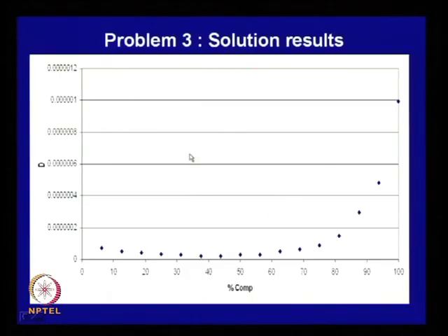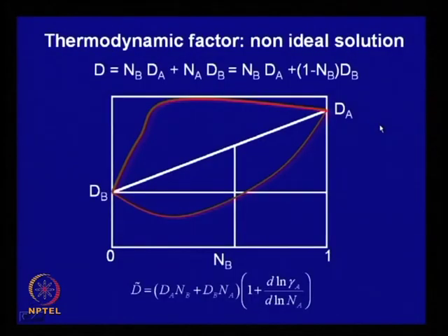Having done this, now you try and plot, and what you find here is that the interdiffusion coefficient is a function of composition. So, these are the intrinsic diffusivities. Similarly, here also there will be an intrinsic diffusivity point somewhere here, but in between, the interdiffusion coefficient initially goes down, then again goes up. So, this is interesting. Let us look at it a little more carefully.